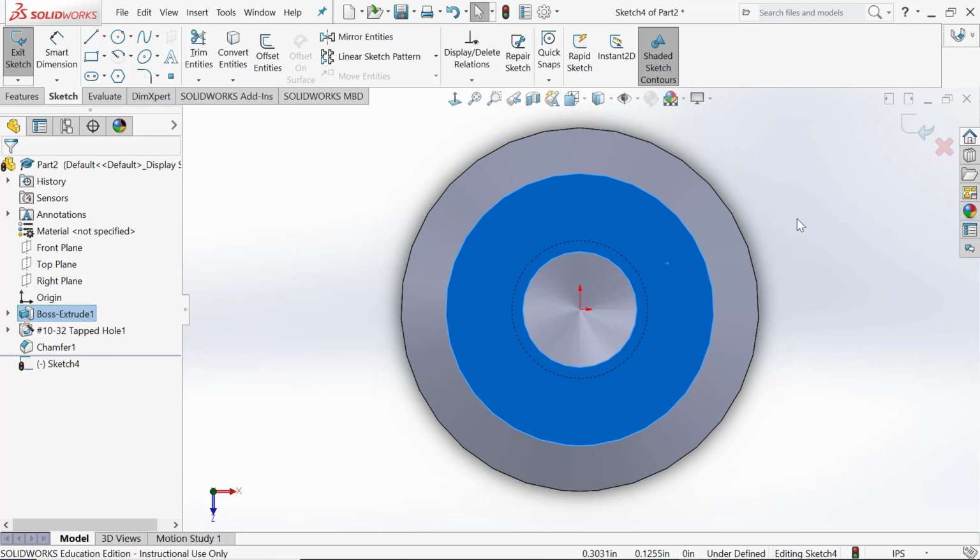Okay, are you trying to move it after you exited the hole wizard? You need to be in the positions tab of the hole wizard to move it. Did you turn off your point tool so you're not making more holes? You should be able to click it and drag it unless it has a green box associated with it already. Does it have a green box associated with it already? Click and drag the blue dot to the center.